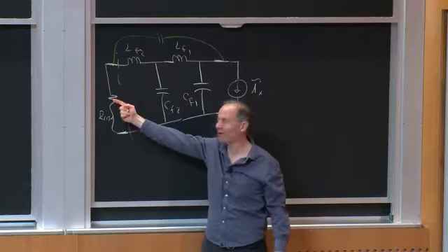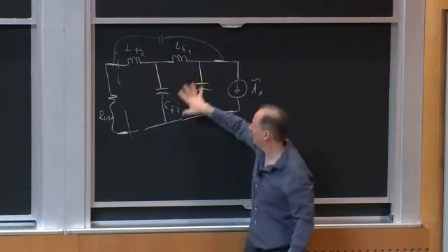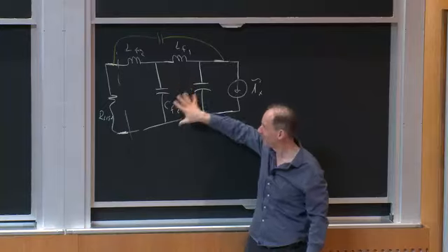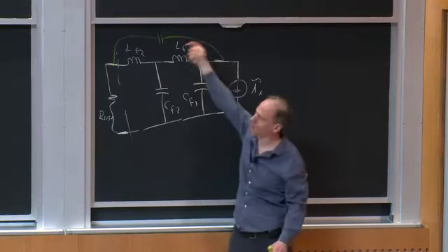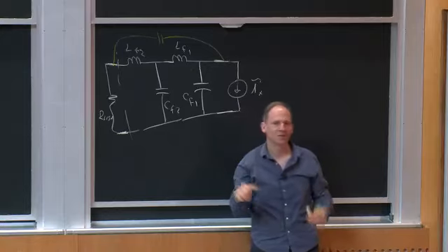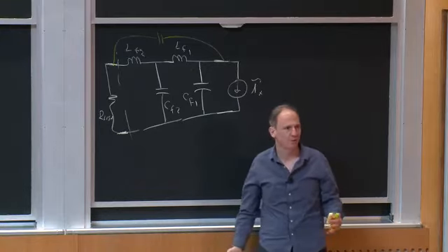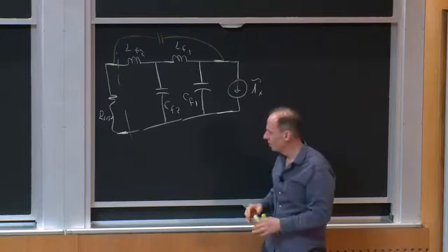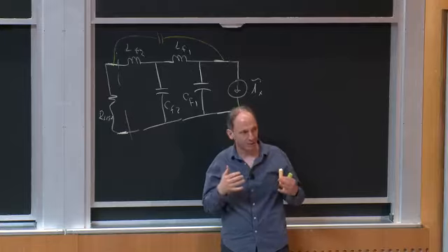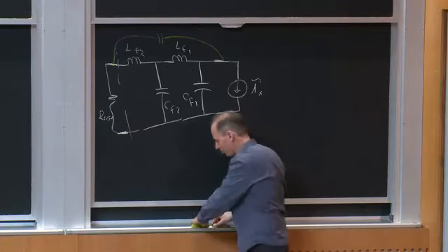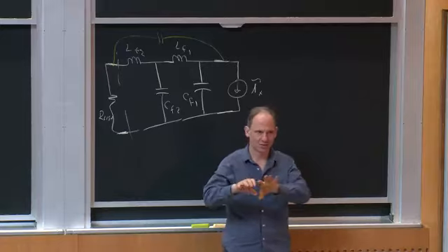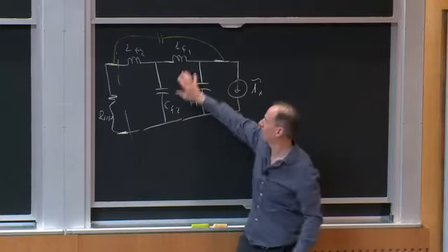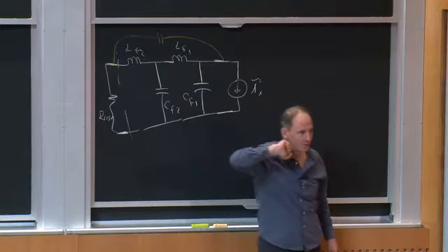So you're getting bad results. You're measuring stuff over here. And you make this filter better and nothing happens. You make this filter better and nothing happens. Why? Because it's not going through your filter. It's going around your filter. All right, and that's the kind of thing that drives people nuts. So you have to think very carefully about your layout. People really try to have a quiet side and a noisy side so that they stay physically far apart so you don't get capacitive bridging.